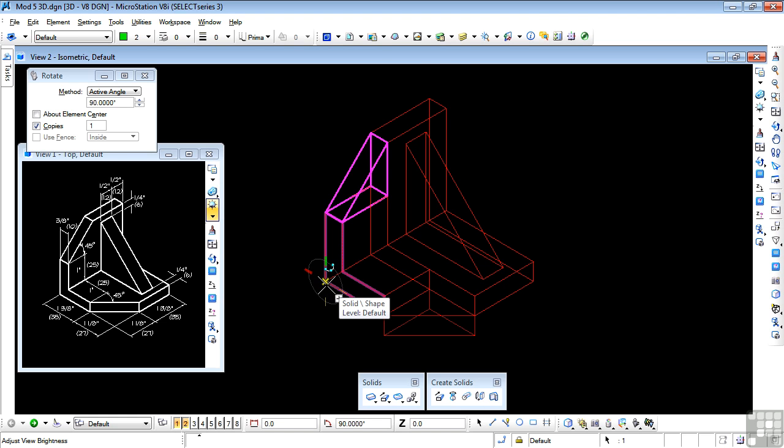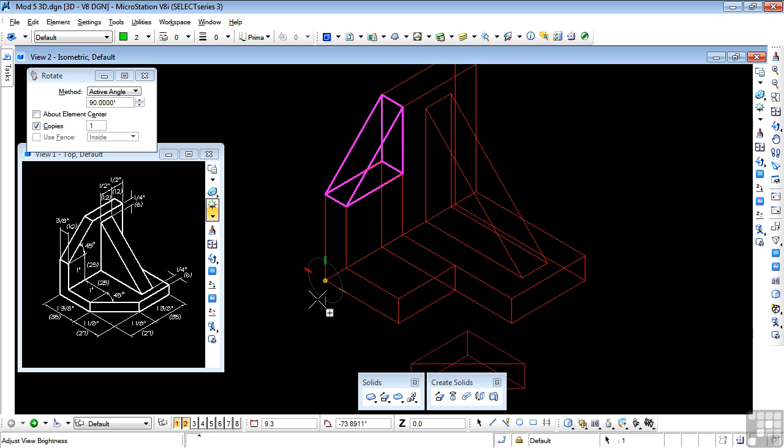Now let's take a closer look at this. If I select this corner here as my rotation point, and the rotation point is key here, notice that the segment is too low in the gap in the lower leg. Okay, let's try the next corner, which is this corner. Now my segment is too high in the leg. So what's happening is that the rotate tool rotates the centroid of the element. In other words, the centroid of my original element is the connection point for the rotate tool.